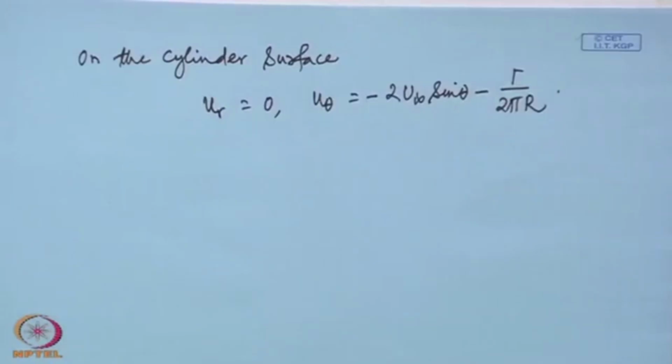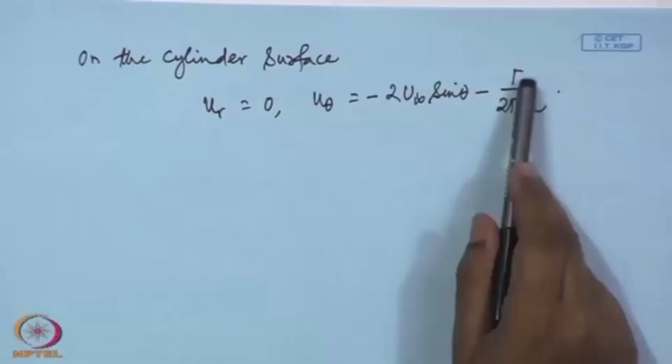The first thing you can see here is that the stagnation points are changed, they are no longer at theta equal to 0 and theta equal to pi. For a clockwise vortex or clockwise circulation, we will see that these stagnation points come below the axis, to the bottom, and the location is of course dependent on the value of gamma.